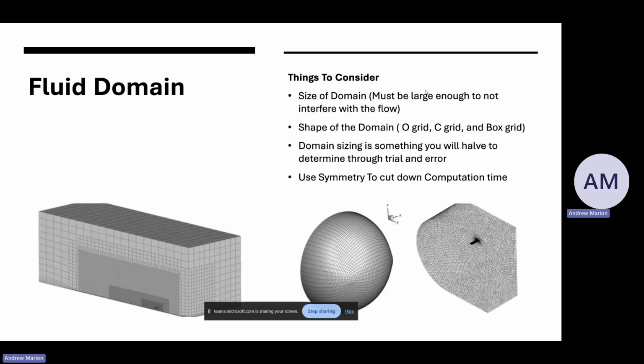Instead of remeshing every time you want to do 10, 20, or 30 degrees, you can just change the components of the velocity coming in. Instead of changing the aircraft, which means you have to mesh again, which takes a very long time, the air comes in at 20 degrees below it. So you get the same effect, but to do that, you need an O-grid so it's not interacting with the walls. Because if you did it on the rectangle, it would hit the walls.